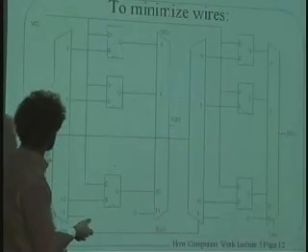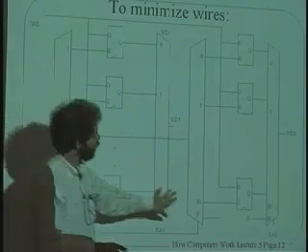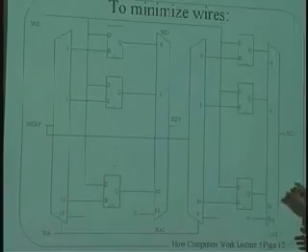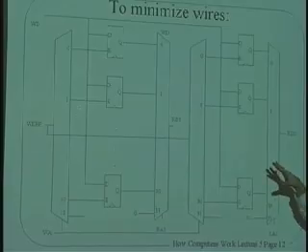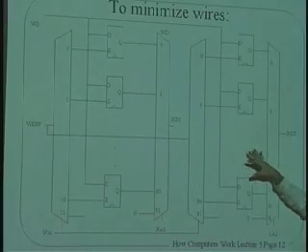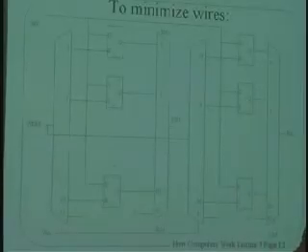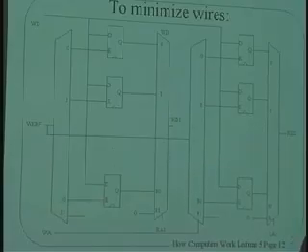And that means that when you access the read port of the left-hand file, you could also access a different register using the read port on the right-hand file, and it would work exactly the same as that other system I just showed you, where we had a single set of storage and the wires went across two different selectors for the two different ports. So this is how to build a two-port register file out of two one-port register files. And the answer is to just sync them up so they both have the same thing on them. Okay, it's kind of a cute trick.